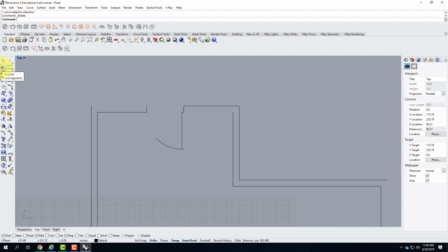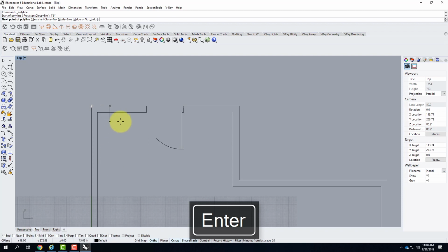I'm going to click on the Polyline tool, and move my mouse over this corner. When I move the mouse over the corner, you see that it snaps to the corner, and I get a little snap box that says end on it. And the point at the corner turns white. I haven't clicked anything. I just moved my mouse over that point. I will then move my mouse to the right, and that little white point turns blue, and I get a white horizontal line. This is that tracking for me. I can now specify a distance from the blue point that I want to start my line. So from that blue point, I want to go over 1'6". I'll press enter, and now my line starts from there.